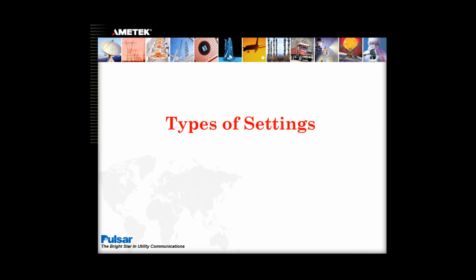Please note, before powering up and making software settings, it is recommended that hardware jumper settings be made on the I/O module, power supply module, and backplane per your engineering department's direction.